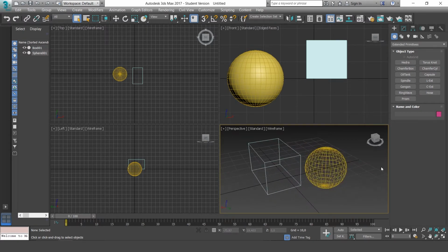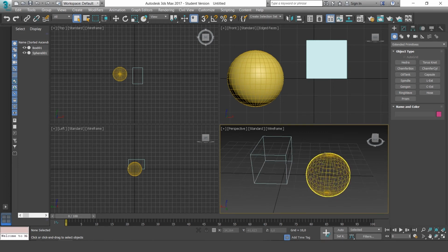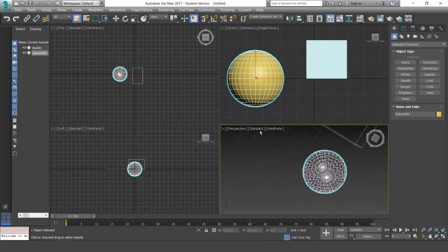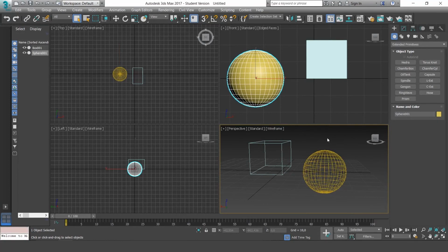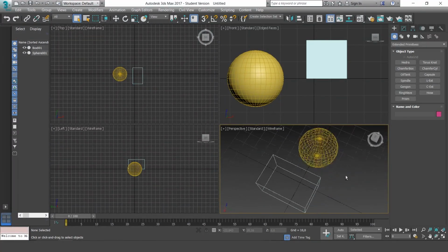And in case we were working on the scene and we get lost and we didn't know where our model was, by pressing Z, we'd go back to the scene. Also, when using, for example, Alt and the scroll wheel to rotate, when an object is selected, our camera will use that object as a reference, which basically rotates around the object. If we didn't have an object selected, we just rotate around the general scene.